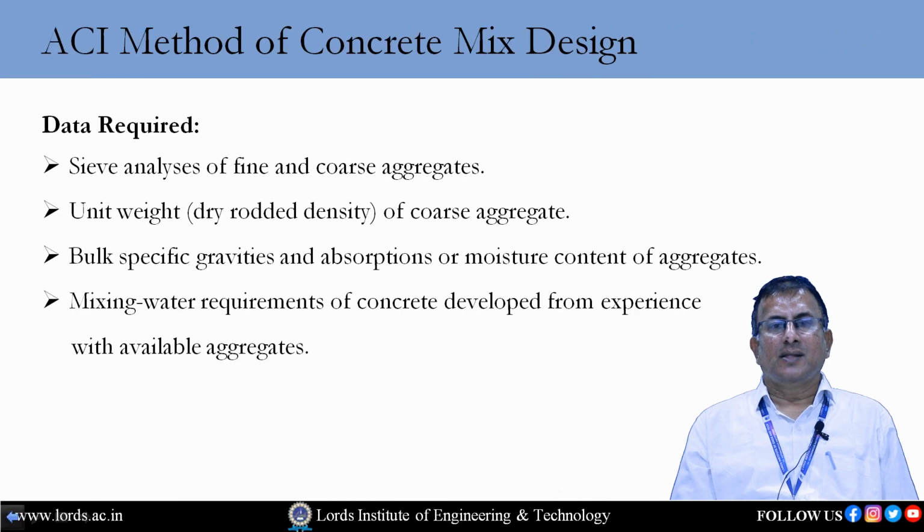Today, the content that I have taken for the discussion is mix design by the American Concrete Institute method. For the mix design by ACI method, the data required is sieve analysis of coarse and fine aggregates, dry density of coarse aggregate, bulk specific gravities and also moisture content of coarse and fine aggregates, mixing water requirement for a concrete,